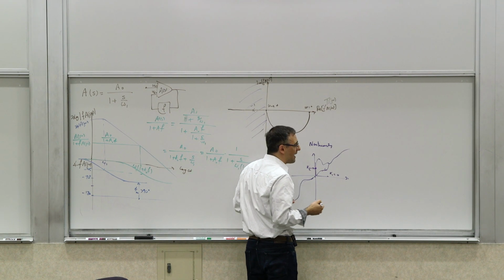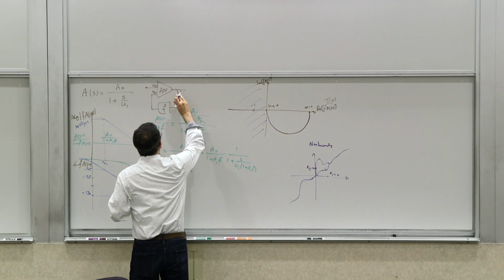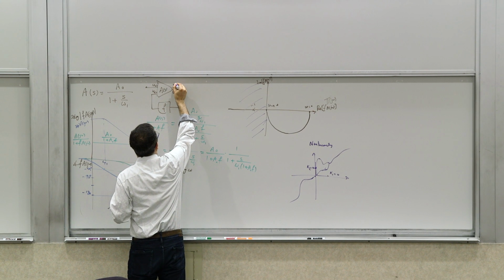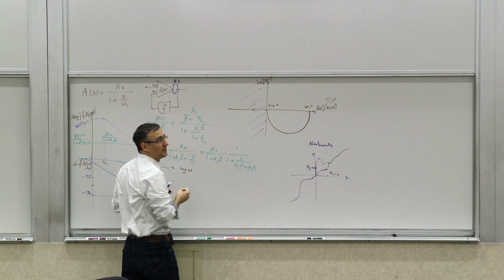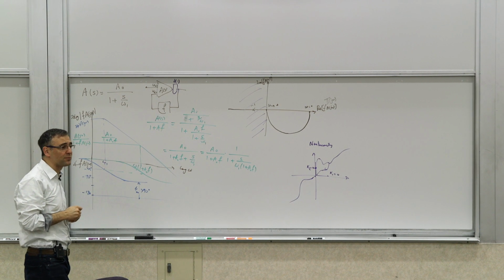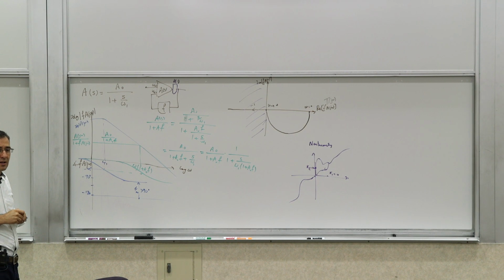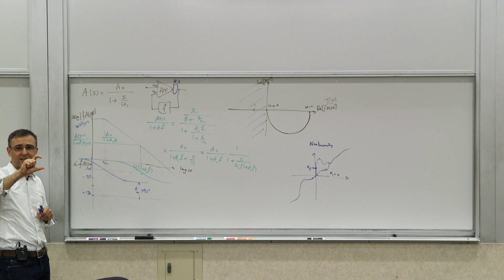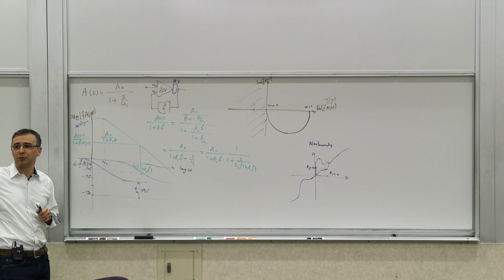Yes, well, it could be anywhere. It could be an actual extra element, a nonlinearity. You can actually introduce it here as some phi dot. So it can be in the system. And this is a criterion for absolute stability, right? Circle criterion is an absolute stability, meaning that you would not even get a steady state fixed amplitude output.